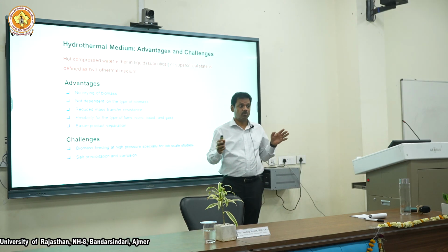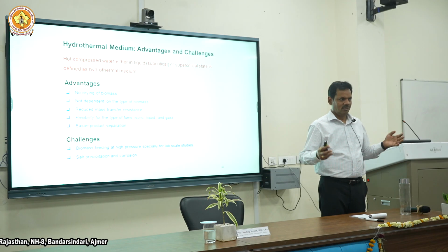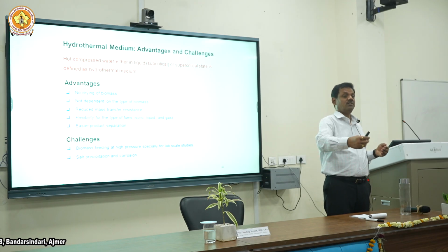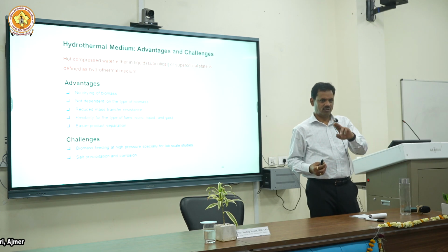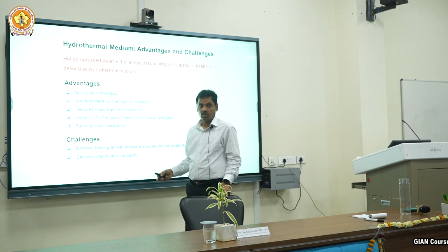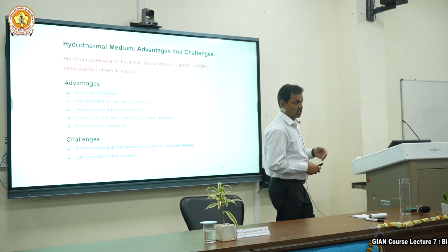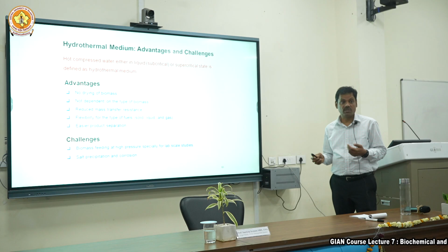Especially with biomass, if you want to feed at high pressure, I said biomass transportation is a challenge. Pressurized, it turns into wet slurry and the water will filter out, so you cannot move it with water. So you need some screw kind of reactor and other things. That's a challenge. Salt, which was soluble at room temperature, will precipitate at high temperature, causing clogging and other things. Those are challenges, but it has very good applications.